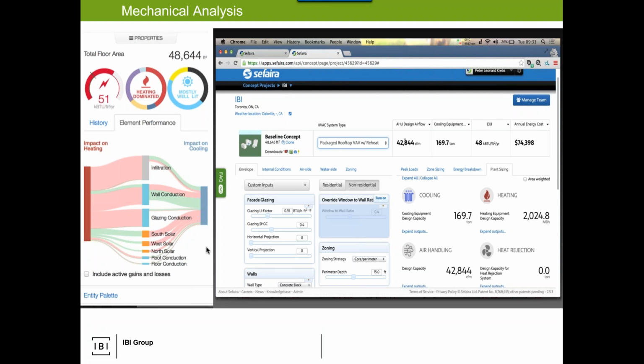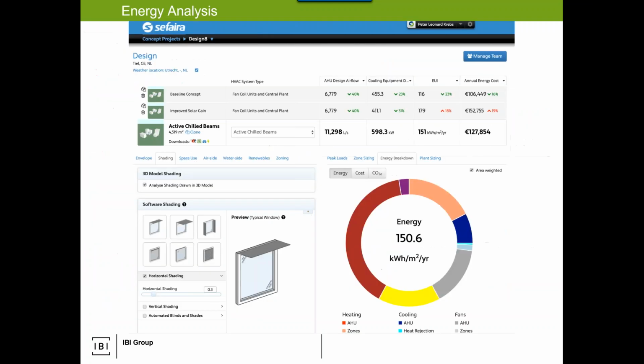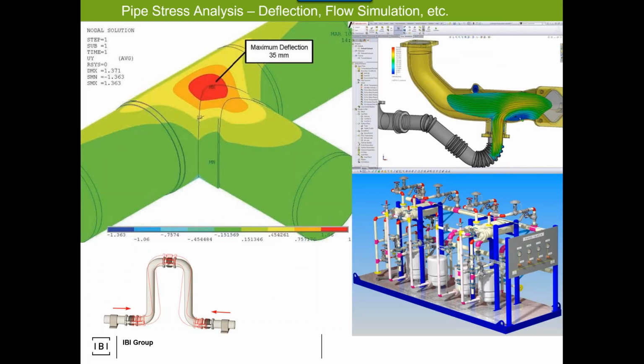Model correctly. You called a wall a piece of glass by mistake, and therefore the heating load is astronomically horrible because it thinks it's a piece of glass going up the entire building when in reality it's not. So all those things, and it's very easy in the BIM world to completely mess up the analytical portion just by having an error in the selection of materials.